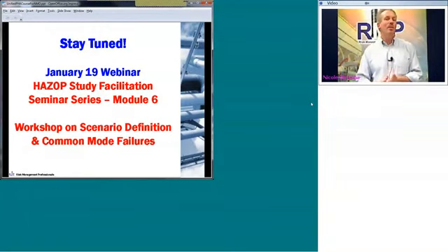All these failure rates, everything else that's done, it's based on achieving the function associated with that safeguard. Now, understanding that function and devising a test program to functionally test the equipment, whether it be an alarm and you're actually testing that the sensor has been activated, or a valve that it's stroke tested that it will actually work, all those go into functional testing. So if you're not functionally testing it, then no, I would not consider it monitored.